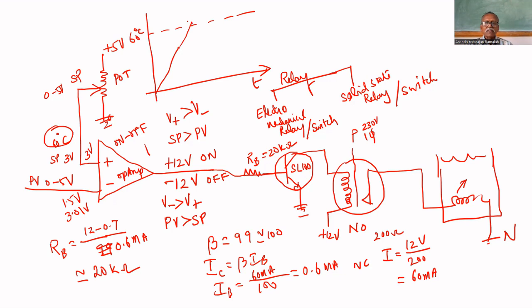But there will be a slight increase due to inertia, which we have already discussed. Due to inertia, it will go up, then go down. Whenever it falls below 60 degrees, it will be turned on again. So it will wander around 60 degrees centigrade. That's all about the on-off controller; you have to do this in the laboratory.